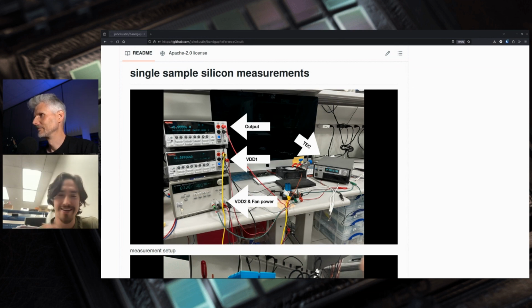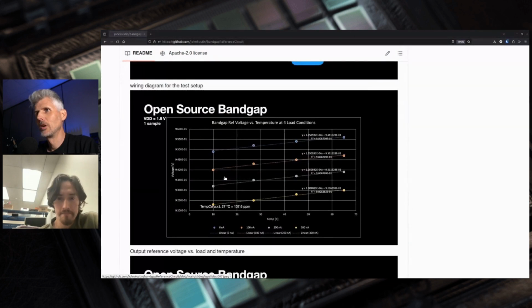And doing the cooling, I would be willing to bet money that anyone who ever wants to test a device over temperature has their device under test and probably needs some auxiliary circuitry or a microcontroller. Be careful that everything that goes inside the temperature chamber hopefully all works at the same temperature thresholds. Because if one thing fails before your device under test, then you're out of luck. And I think that was what happened to me in this testing, where I wanted to go to a wider temperature range, but we were limited in what we could realize because of a microcontroller; we could have broken it. We pushed it too much. So let's move to one of your cool graphs then.